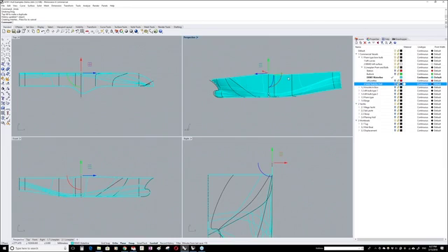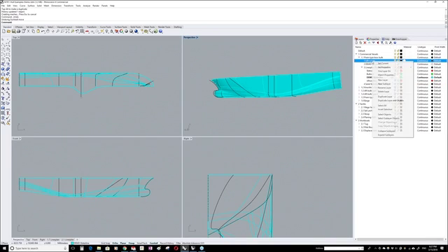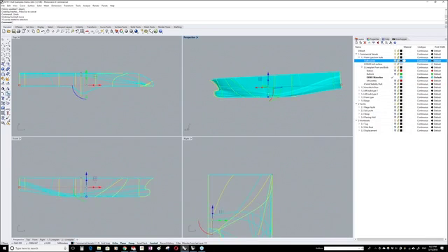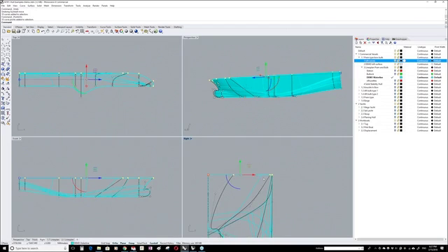Yeah, that's one thing. Very good that you show this, Bas, because that's what I see a lot with people who model ship hulls: they don't extend a hull up enough, and then they create a second one in the bow area to extend the hull, and then extend it a little more even in the superstructure. So you can often better extrapolate a hull too high and then cut off the protruding part later.